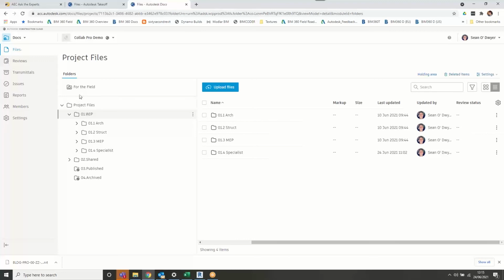When you upload those to the files area of Docs, the architect will have the mechanical layout, no problem at all on all their drawings, but they won't have the structural columns, because they're only linked through the desktop connector. But within their Revit environment, they'd be able to see all the files, no problem. It's just something to be conscious of.